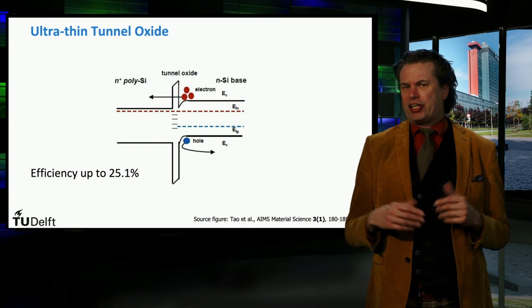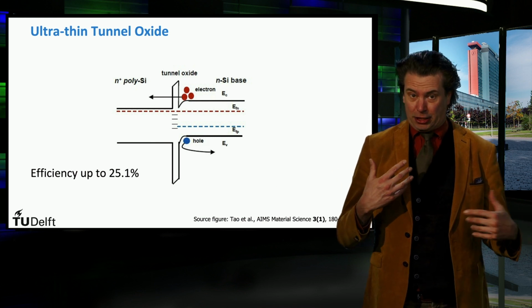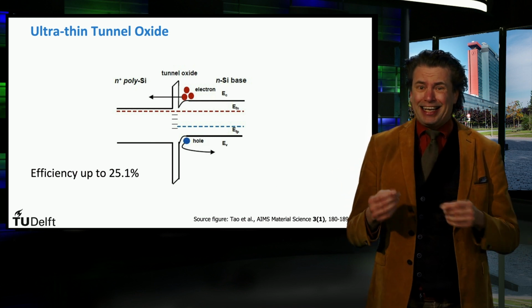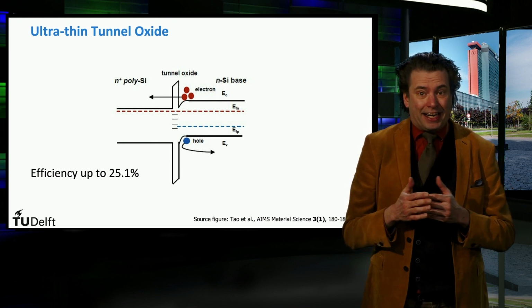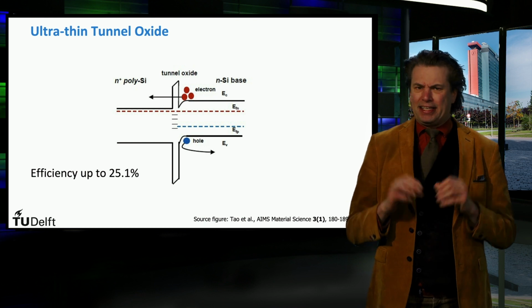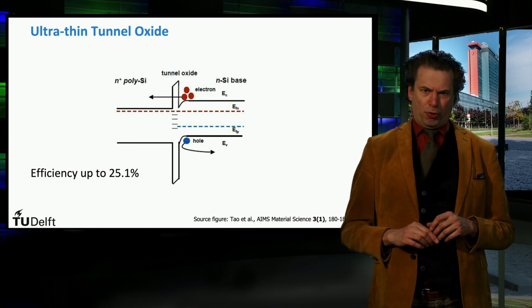Contact patterning, which is a relatively difficult and expensive processing step, is therefore not necessary, and the backside of the wafer can be entirely metallized, making this technology cheap in processing.